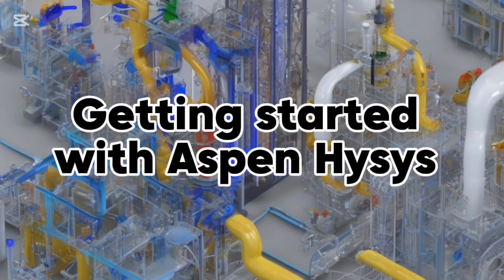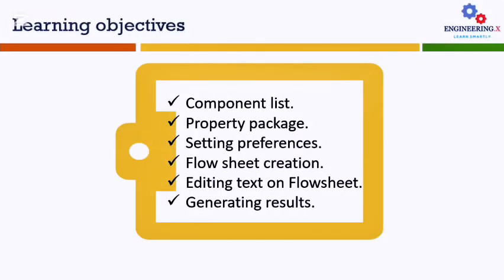In the first tutorial, you will mainly learn how to create a component list in Aspen Hysys, how you can select the right property package for property estimations, and then you will learn to set different preferences in Aspen Hysys, for example, different unit sets. Then we will create a flow sheet, and you will learn how to edit the flow sheet in Aspen Hysys. Ultimately, at the end of this tutorial, we will generate results for our problem.